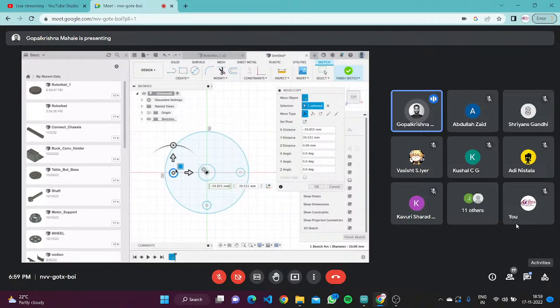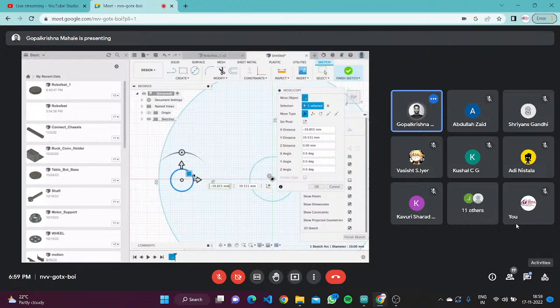If you want to place this precisely, please don't use the technique I am using, holding this block and moving it. What you can do is use the grid value. For example, if I want this to be exact at minus 40 mm, I'll just type minus 40, or I think minus 4, something like that.